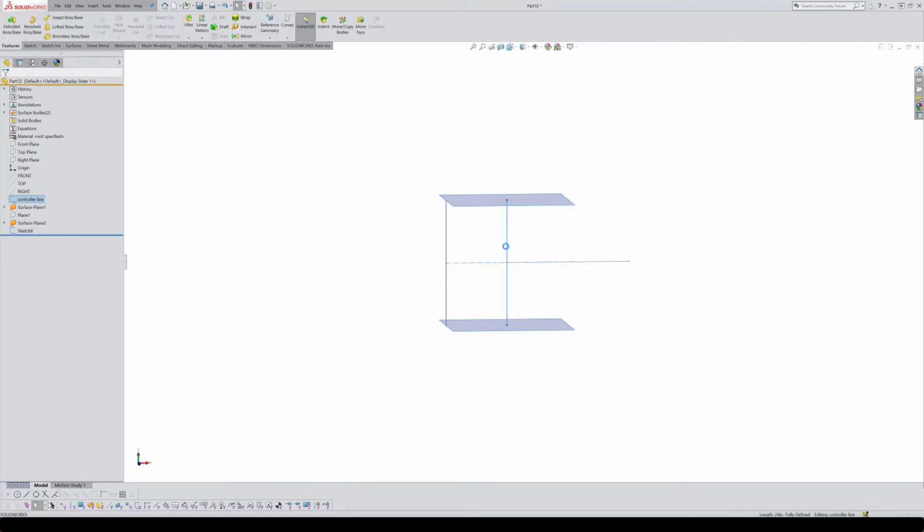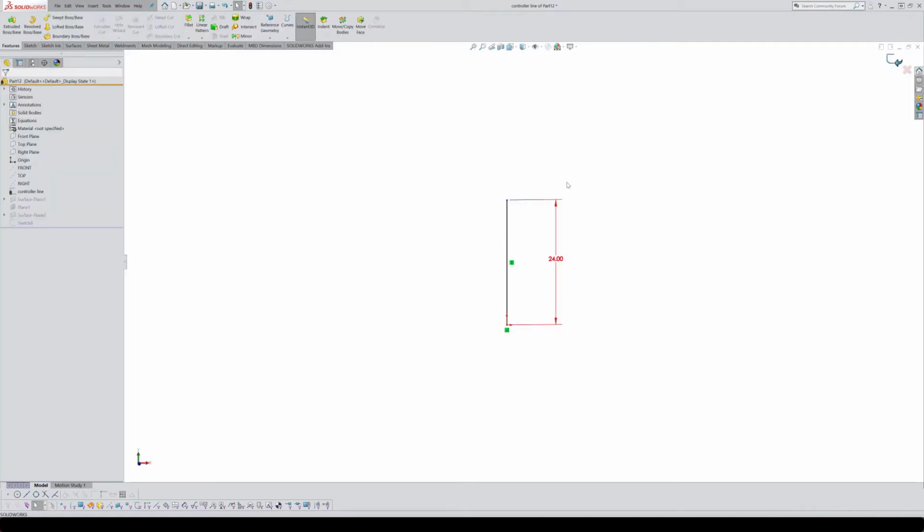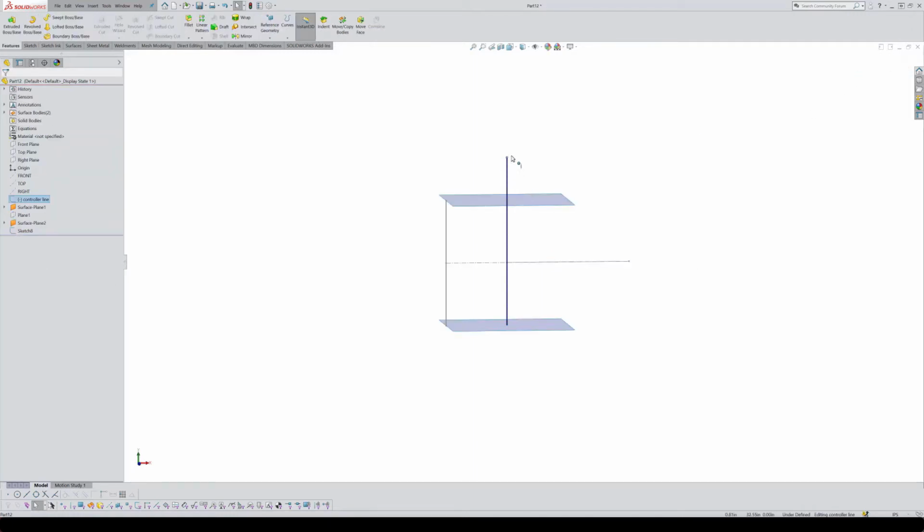If I run a test here, grab this and say make driven so the end is loose. As you can see, if I stretch this line longer, it pulls in that 36-inch line, and those 2 lines follow it, which is why it was important that it couldn't be vertical. And the opposite, if I make it shorter, it'll shove that 36-inch line out and create this new angle. So that is our sketch mechanism. You could see that mimics the buckling and the bulging behaviors that I need from my box.